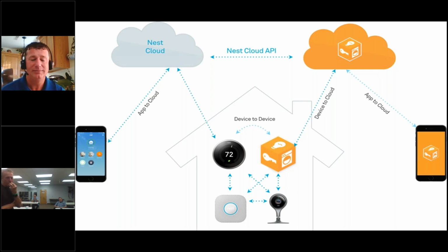No one wants to do that. You're going to need to be able to go into that house and go, yeah, I'll sell you whatever equipment you want. And yeah, I love that you have your Ecobee thermostat. I'm going to go, actually, we're going to set it up for single stage heat and single stage cool. So it's just 2 switches. And I'm going to use that to run your new 20+ SEER outdoor unit and your new 98+% indoor unit. And it's going to be a happy customer.